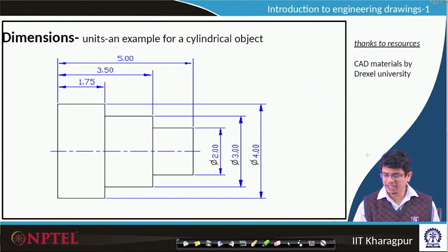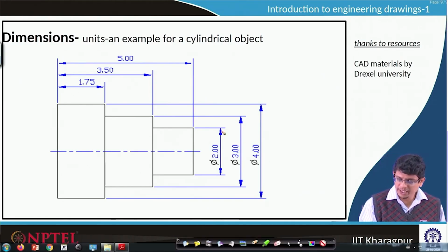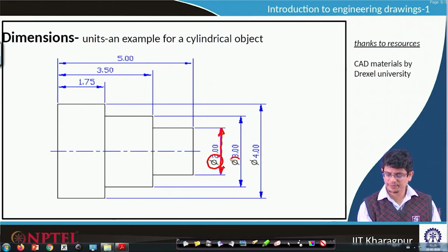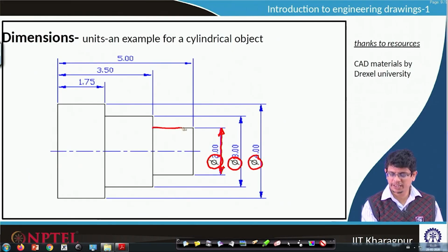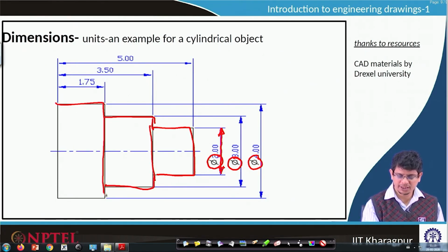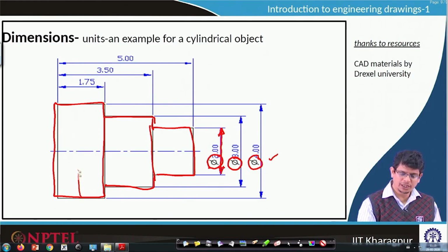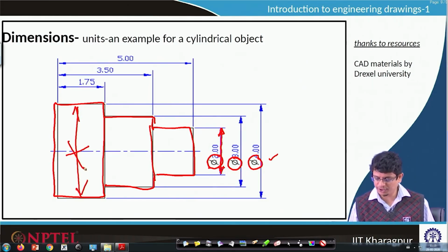Similarly, if these are cylindrical objects, we showed the major diameters outside of the object through the symbol phi. So, here it is one cylinder, a step one, and again we have a step one. So, smallest dimensions inside and largest dimensions outside. We usually do not show anything inside of the object, that is a wrong way of showing the dimensions.